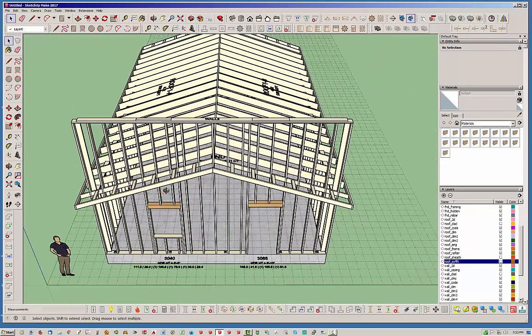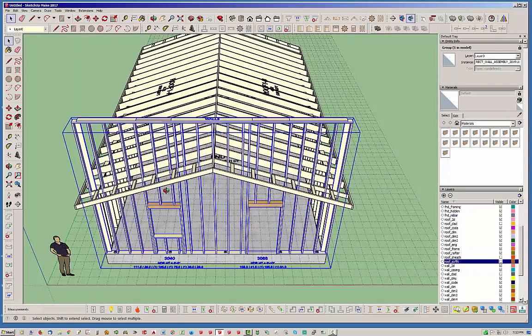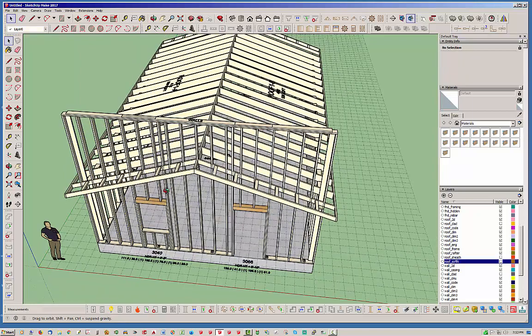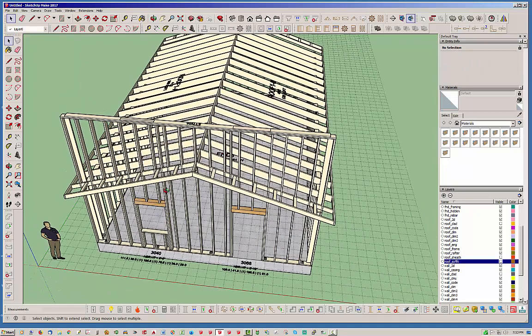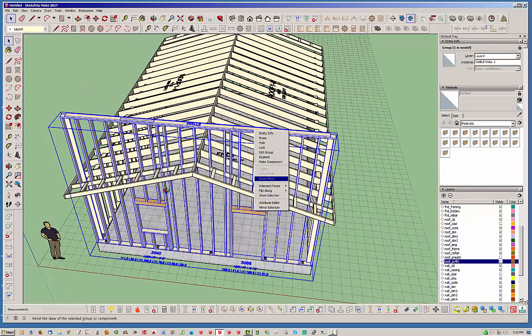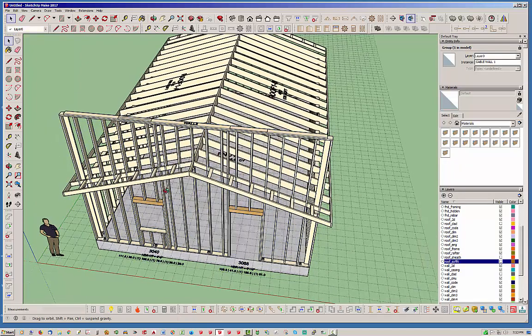But before I do that, I'm going to take this wall assembly, and as you notice here, you've got a keyword in this instance name. If I remove these keywords, and I'm just going to call this, for instance, Gable wall 1, by doing that, now I've locked this wall from editing. If I try to edit it, it no longer has the ability to edit it.